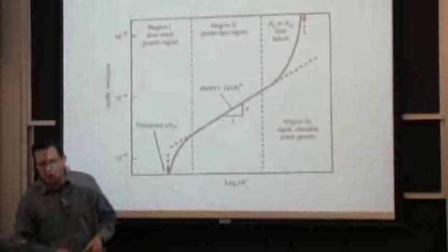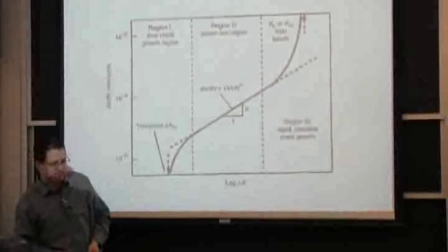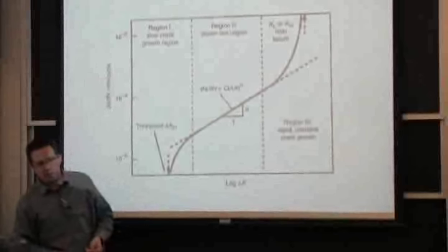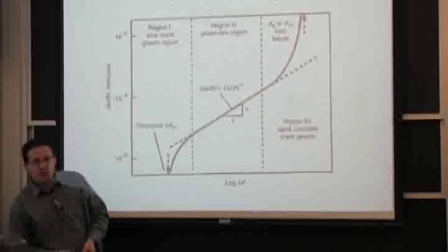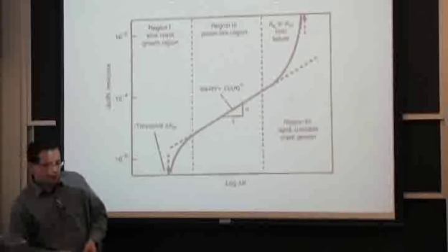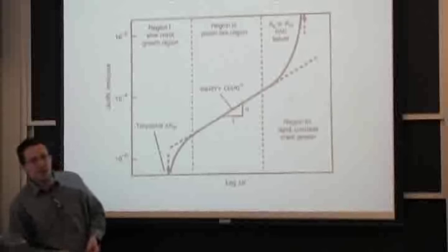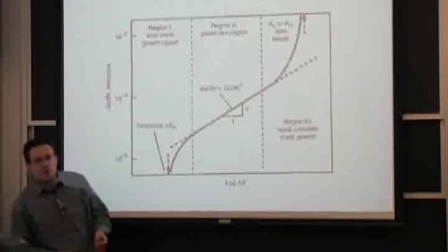It could be a notch. It could be any form of machining defect. Or it could be an impurity in the aluminum. Aluminums, they're so reactive that when they make them in the factory, they always have a lot of inclusions in them.